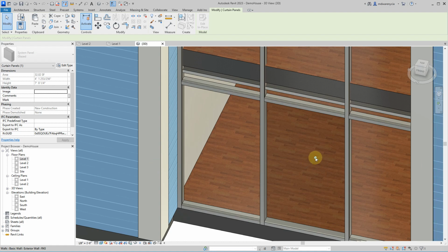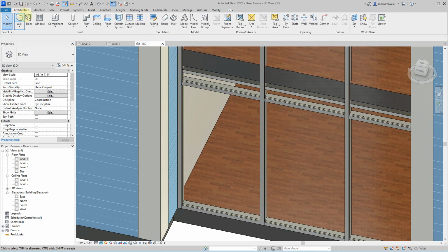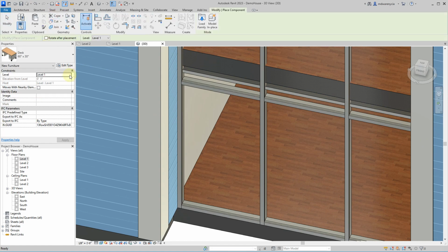If we hover over it, it says prevent or allow change right now because it's hard to see, but when it looks like that, you can change it. So it's unpinned. When the pin is facing to the left, that's unlocked. So this is something we can now modify. I think I've shown two people this semester. It's a thing that comes up from time to time.